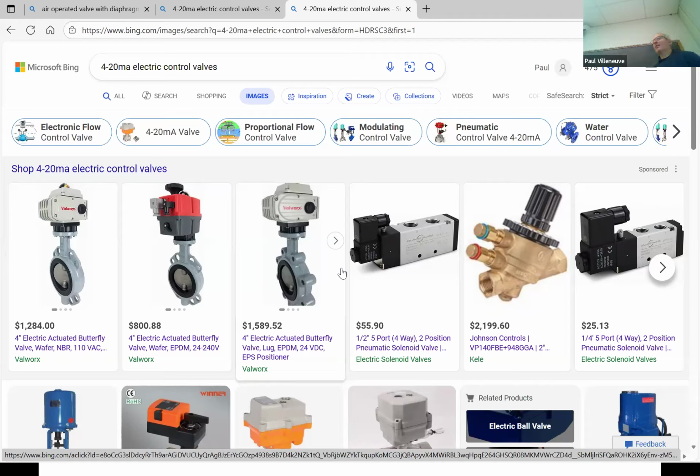Anybody here ever been to an auto shop? Yep. When you walk in, what do you notice? You hear a lot of the big old pressure tank leaking, the compressor, right? So can you imagine you have 5,000 valves with little 1/4 inch or even 3/8 inch lines that would run all over through the plant. They'd have a common header and these tiny little valve lines that would go and control these valves. They were constantly fixing air leaks.